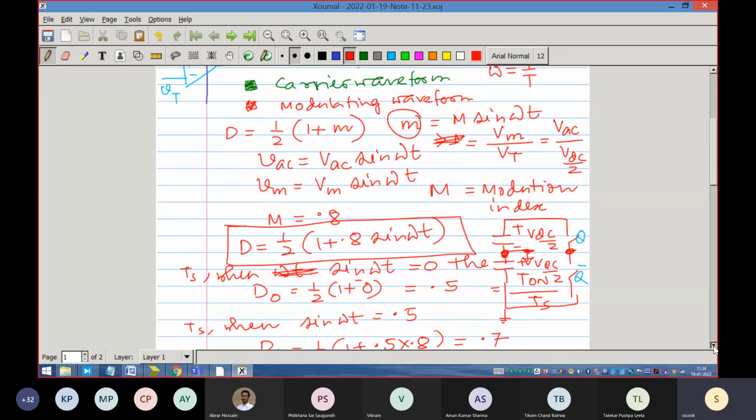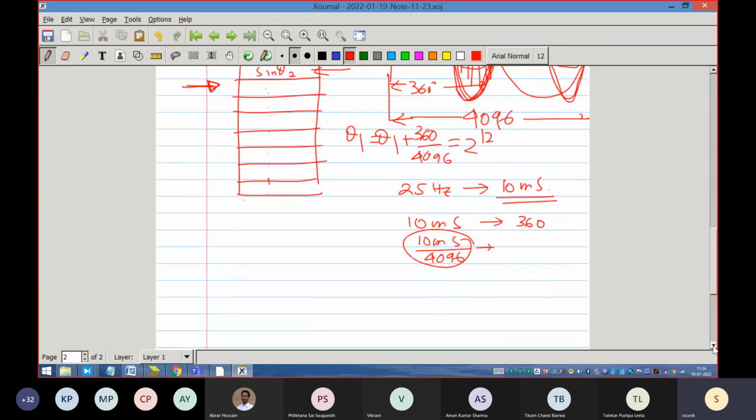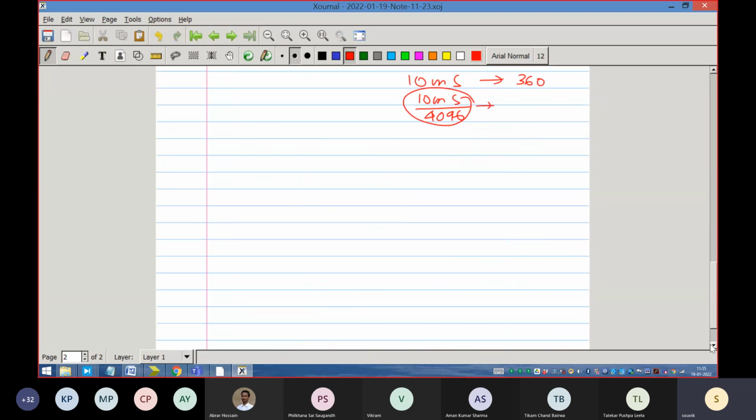Let us first continue. Somehow we have got this pre-stored sine wave, where sine theta is there, but sine theta is not enough, because we have to produce a sinusoidal waveform of different frequencies. The modulating waveform has a frequency, because, you remember, V by F is our principle. So we have to change the voltage, we have to change the frequency. As the modulating frequency is changing, logically we have to change the sine wave also. It cannot be a frozen sine wave. It has to be a dynamic sine wave of different frequencies.